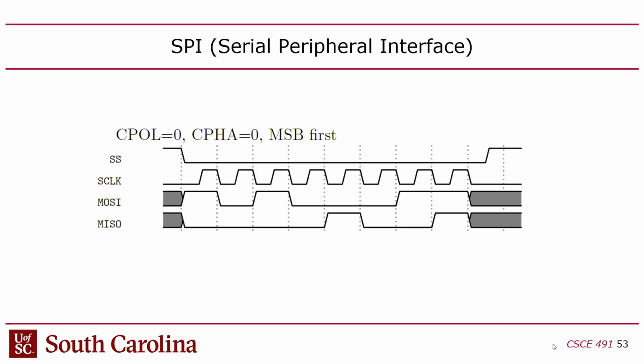Now, whenever you're using CAD tools like the ones we use in 611 and 313, because all communication is happening on one chip, the CAD tools statically guarantee that you will never have that situation because they do a timing analysis and a timing closure. But when you have a communication protocol in which you have two independent systems communicating, it's a lot tougher to guarantee that you don't have this case where you're changing a signal and reading the signal at the same time. So that's what this is all about with SPI, right?